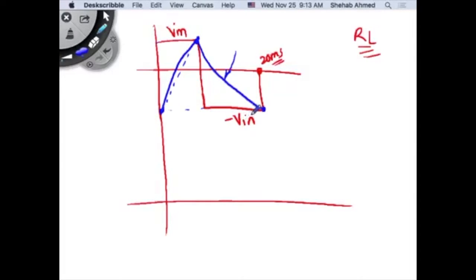If that's the case, that means I have some voltage harmonics that will not find a corresponding current harmonic at the same frequency, and hence will not be able to transfer real power. Is that good or bad? Bad, because I want to deliver AC power to my load. But I have current flowing that is not contributing to P equals V times I cosine phi, which requires Vx, Ix at the same frequencies. If there are currents that are not at the same frequency, then it's useless. I'm not contributing to real power, right?